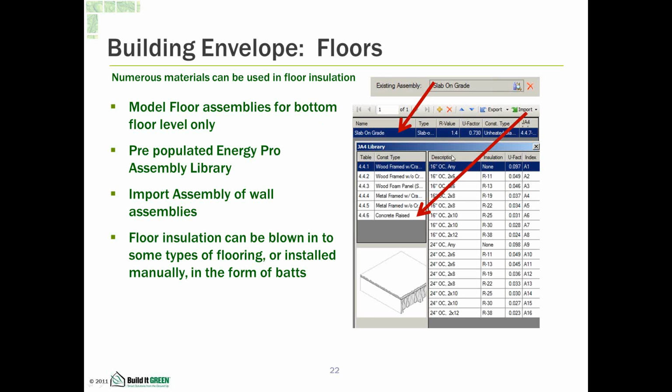Energy Pro also has pre-populated assemblies, and if you want to import, again, you can hit the import button and you can see the library, and you can pull in the assembly, whether it be a raised crawl space, no crawl space, or if it's a raised concrete for a parking garage of some sort. So that pretty much wraps up the floor assemblies. They're pretty straightforward, and you're only going to be modeling that for the bottom level, the first floor level.